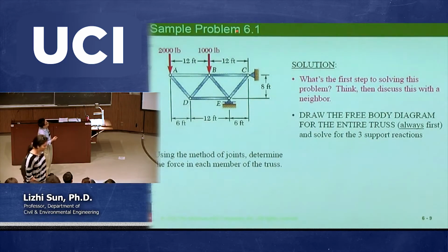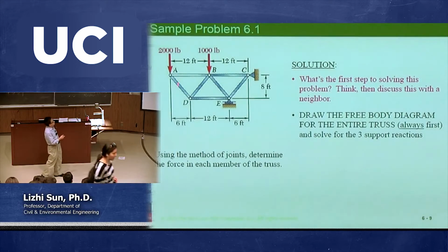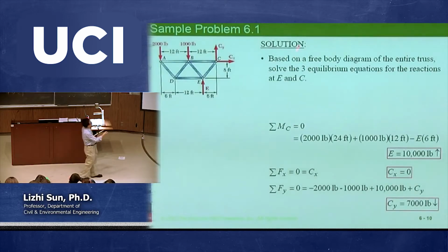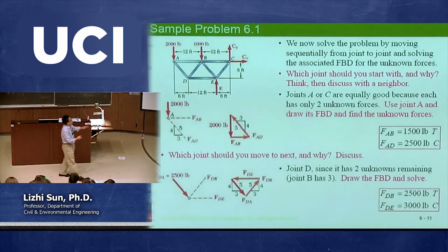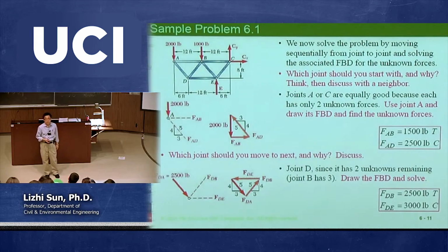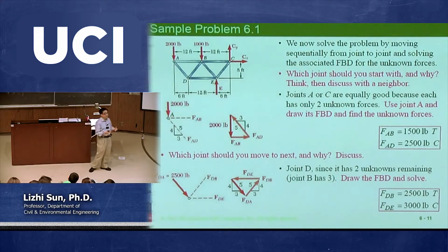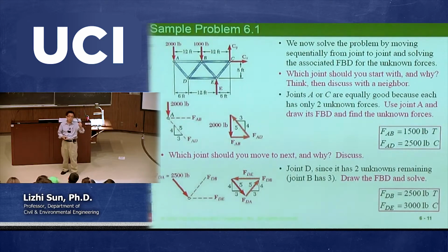In terms of the method of joints, after the first step, calculating all the reactions, we just finished. Then we need to look at joints, and that's called the method of joints. It's really up to us how we pick joints, but the fundamental policy is that you need to look at a joint at the very beginning with only 2 members connected to it.